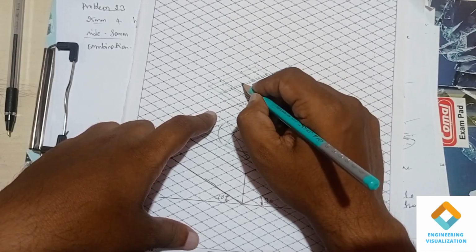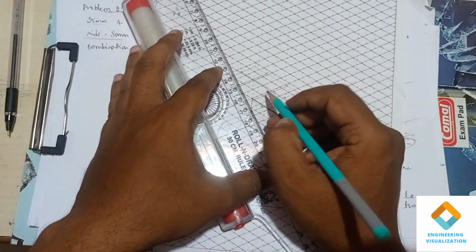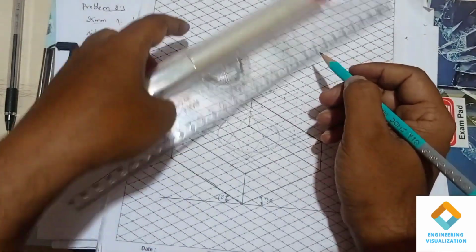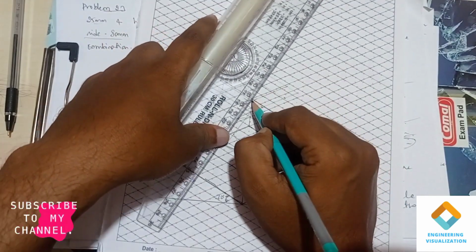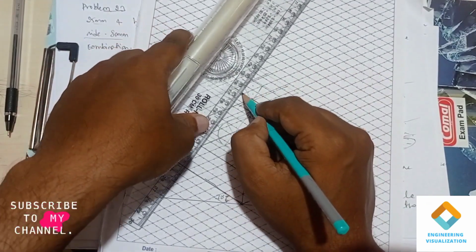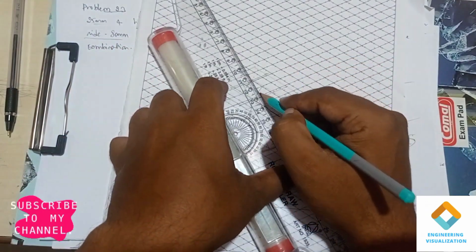Again we use the 4 arc by center method to construct another ellipse, because that is a frustum of the cone. In a frustum of cone, both top and bottom are circles. So when it is constructed in the isometric, it becomes an ellipse.